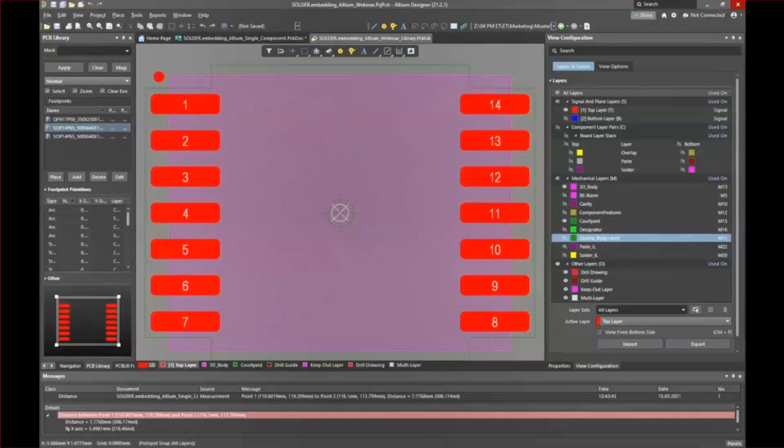And again, I am using Altium Designer as an example, and I would like to demonstrate the additional mechanical layers. I have already opened here the PCB library for this purpose, and the component was first defined in the library with its footprint on the top layer, as I mentioned, and it only turns into an embedding component when it's defined to the actual layer in the used layer stack in the layout phase.